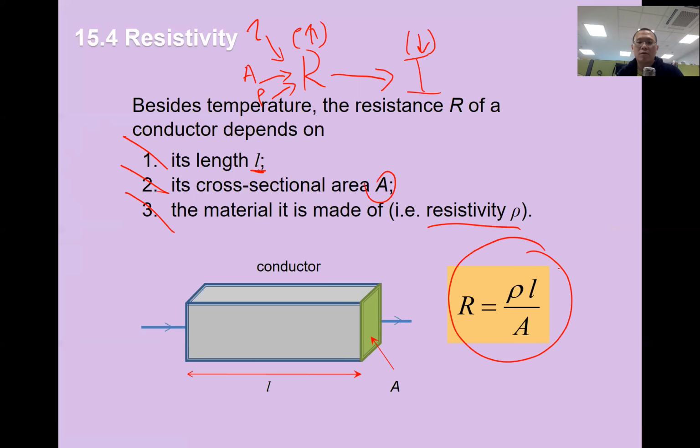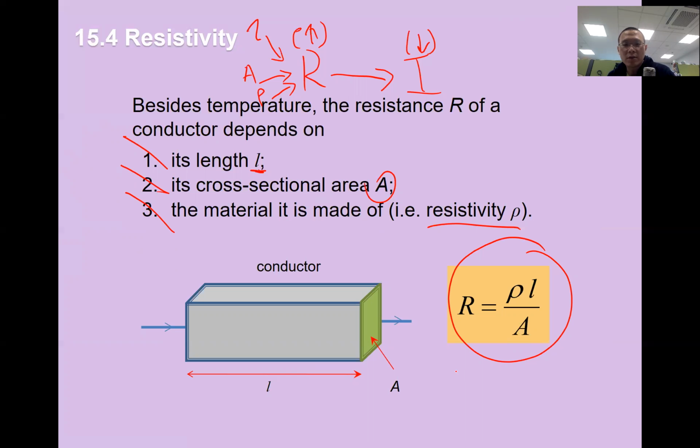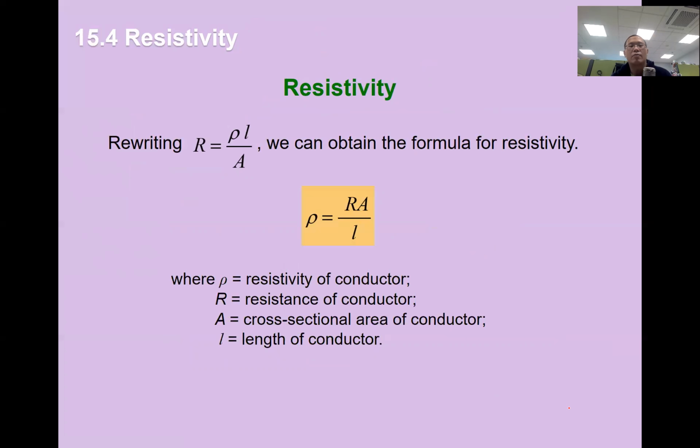So we can loosely say that your resistance increases when the length of the cable increases, or the cross-sectional area decreases, or the material changes and the resistivity increases. So at the end of the day, if any of these three factors change together or individually, you'll find that the resistance will change, and vice versa. Now, this is what we mean by the formulas.